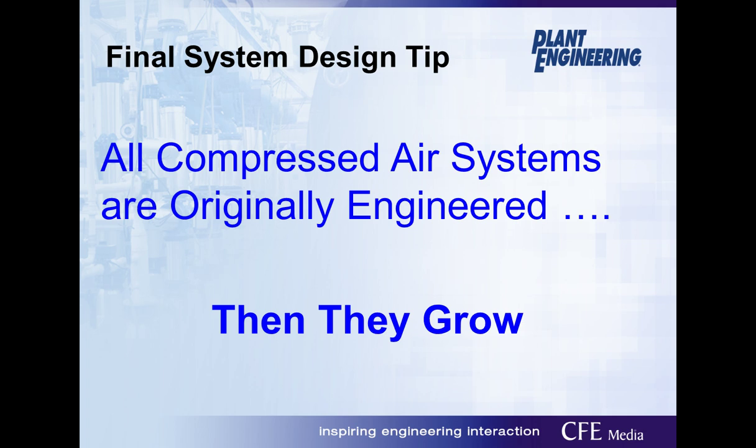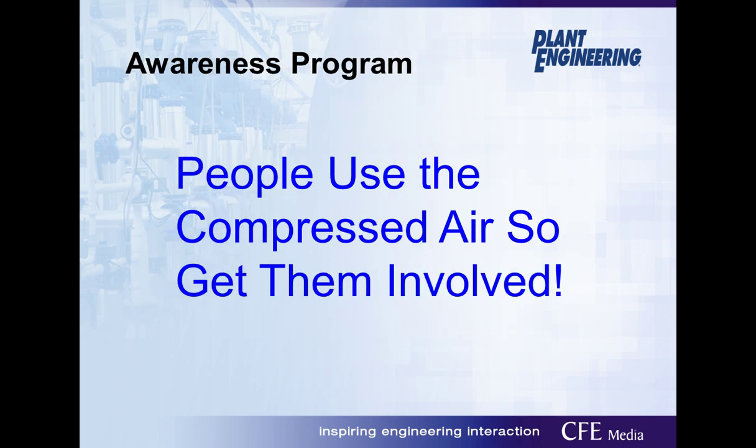And the final design tip that I want to leave you is that all compressed air systems were originally engineered and then they grow. The real truth is when you're in a manufacturing facility, over time things change, processes change. You have to look at your system and keep evaluating that system and its efficiency. That's why we talk about understanding the supply and the demand, because the dynamics are constantly changing over time. You want to understand that to keep maintaining that system integration and efficiency. And another big part then is awareness.